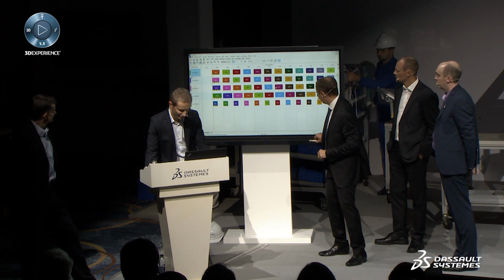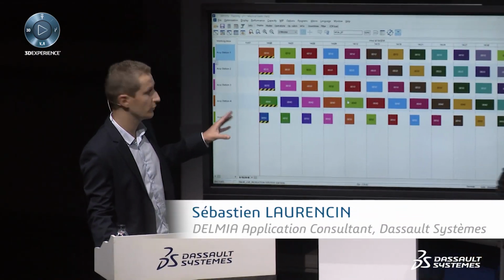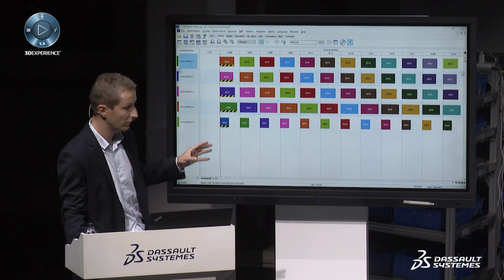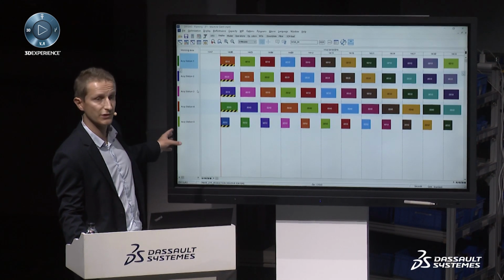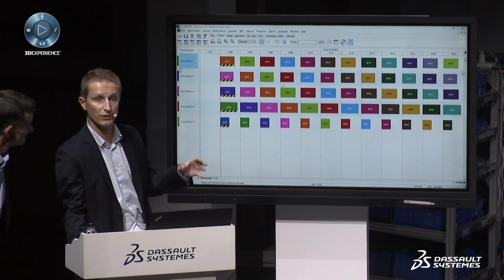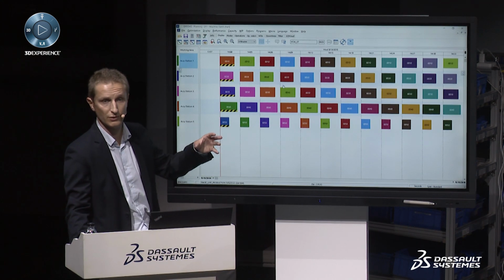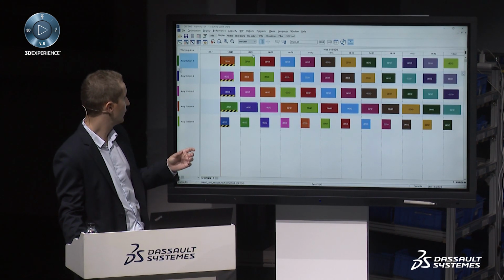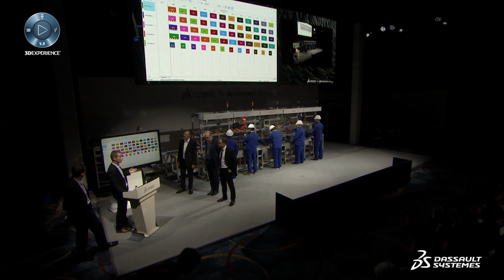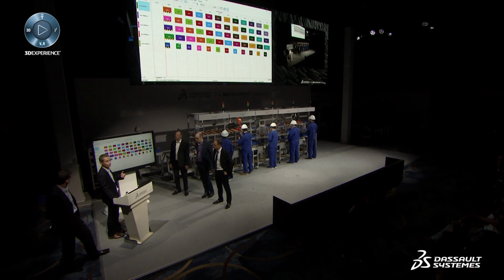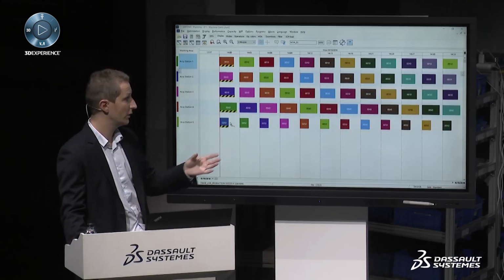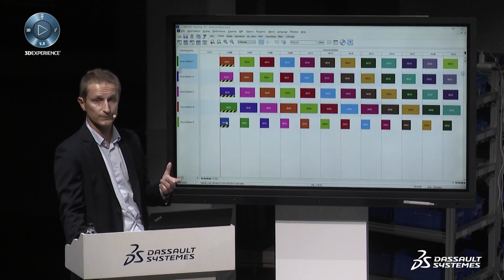Have a look at the production plan. Here we see the current production plan of our assembly line. On the left part, we have the different stations from 1 to 5. And on the main screen, we have a Gantt chart with all the operations of my work orders. We have here the 3-minute takt time. That's the current rhythm of the line, and that's why all the operations are vertically aligned. The first operations are in progress because the line is, for the moment, still running.